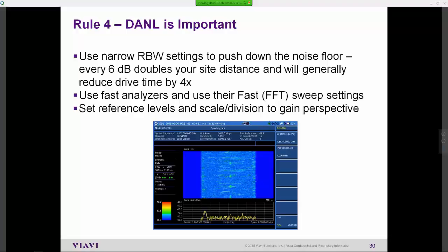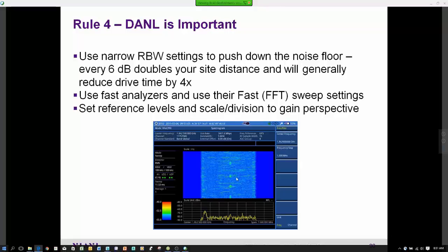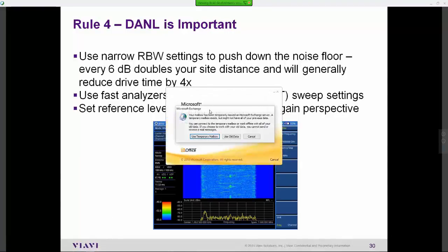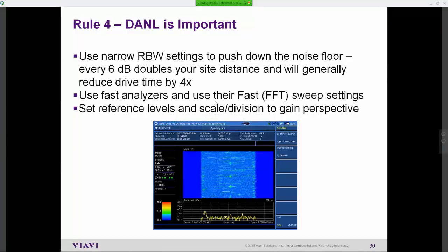Now this last point is a huge pet peeve of mine, and even on this display, it touches a nerve, because as I look at the spectrogram display, which is one of the single best displays to use for interference hunting, I see two colors. I see green and I see blue. Although the interference in this case is quite obvious, because these little blips in the middle are not characteristic of an LTE signal.